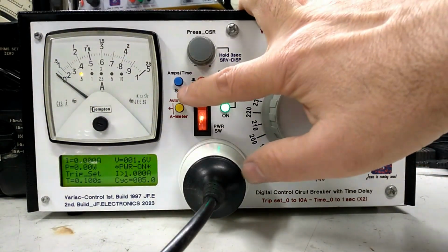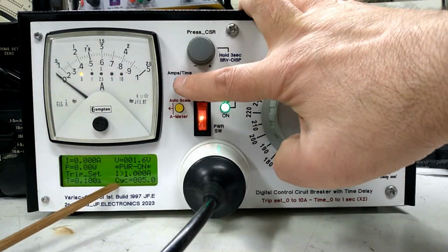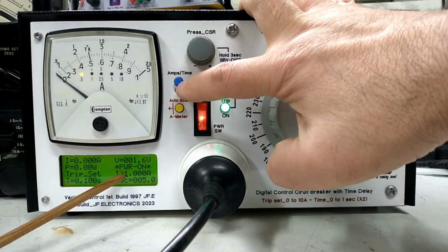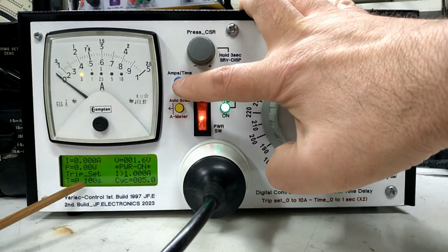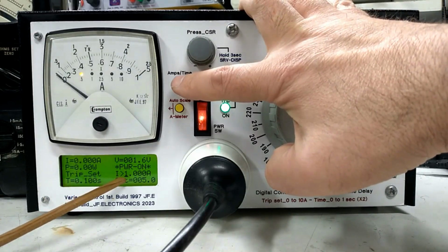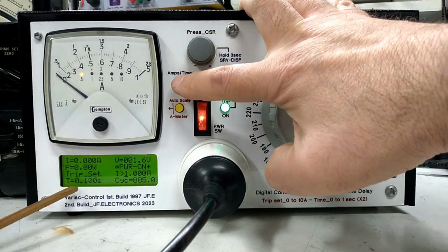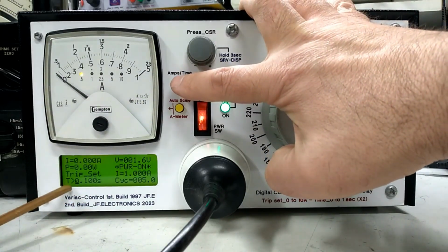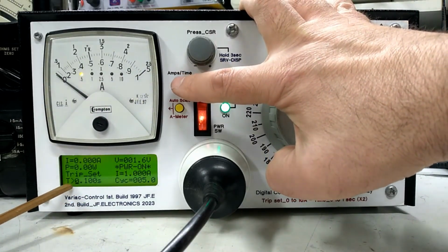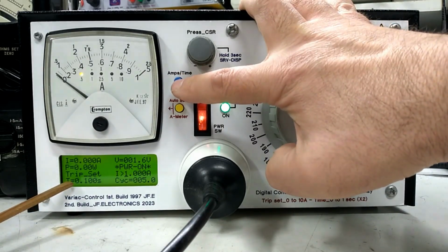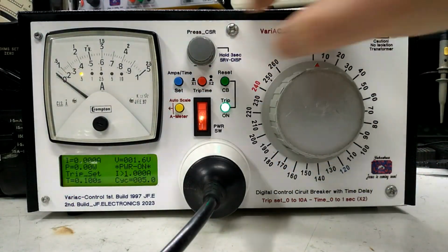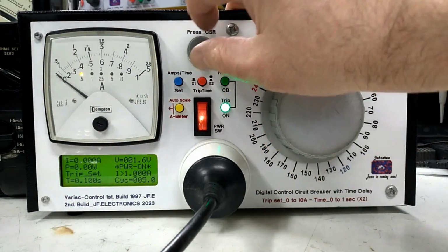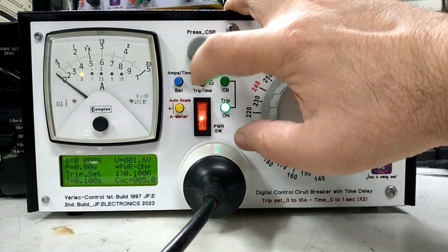And then the other button is to whether I'm going to change the amps, trip time, or the time delay. So it's a toggle between the current and the time. So you can see now the arrow is on the time. That means I can change the time. If I press it again, it goes back to the current. So if I change the current,